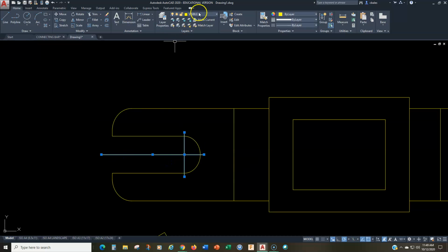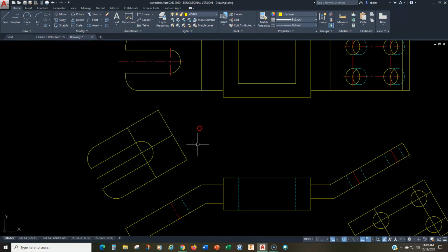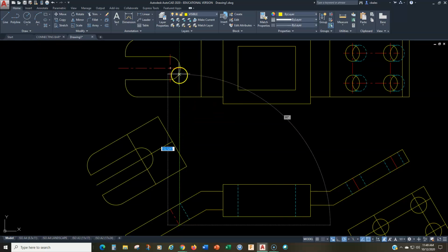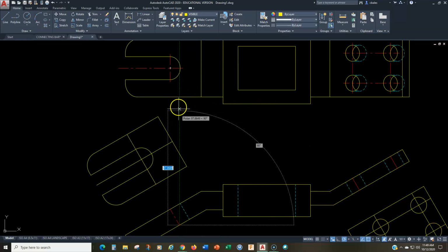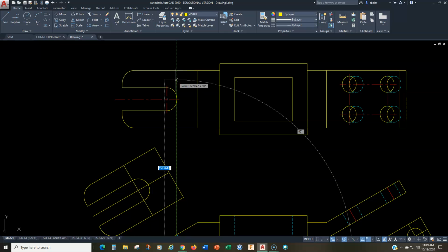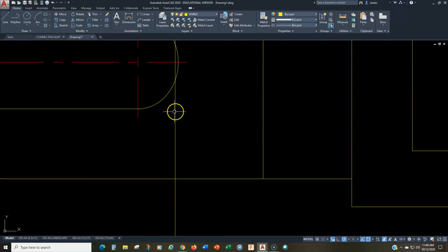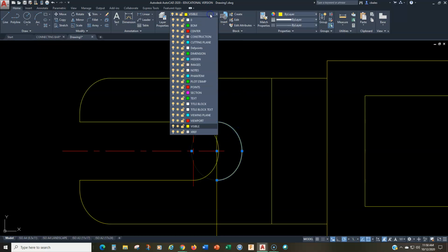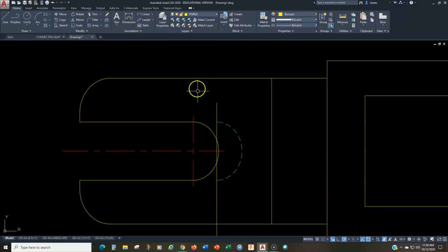And let's turn these into the center layer. There we go. And yeah, there's going to be a hidden part. So let's find out where that is. The center of the hidden part is going to be right there. So we project, notice we project it up from the bottom surface, and we project it up right. Right there is good. And then we're just going to copy the curve from the center here to the center there. Okay, now this becomes a hidden curve.